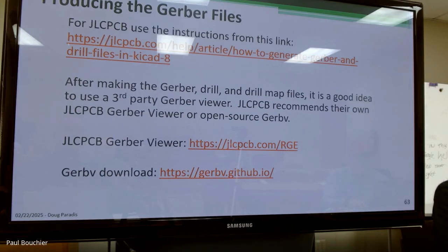Now, this dirty little secret: if you just package up the Gerber files with the defaults that are in KiCad, it works. But you should check all of this, because they might have something a little different. When it was in 7, I very religiously looked through this and made sure all the little buttons were pushed. You'd find that 99% of them were, but there might be one or two that they changed. When I just hit the defaults, I've never seen any problem because of it. But your mileage may vary.